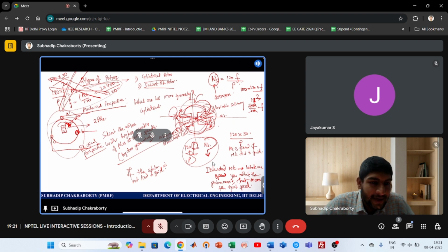So if I rotate at 100 RPM, I have low frequency. If I rotate at 1000 RPM, I get higher frequency. But remember, the synchronous speed is still 100 or 1000 RPM, whatever is the speed of the movement with which I am rotating the prime mover. But what happens for grid-tied machines, either generators or motors? I have no other option but to rotate it at such a speed that the generated EMFs have a frequency same as that of the grid. Otherwise, you cannot connect them.